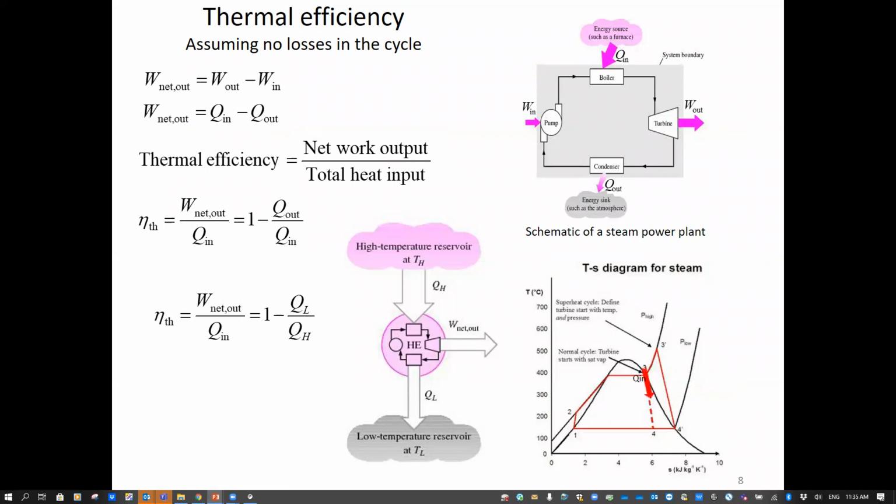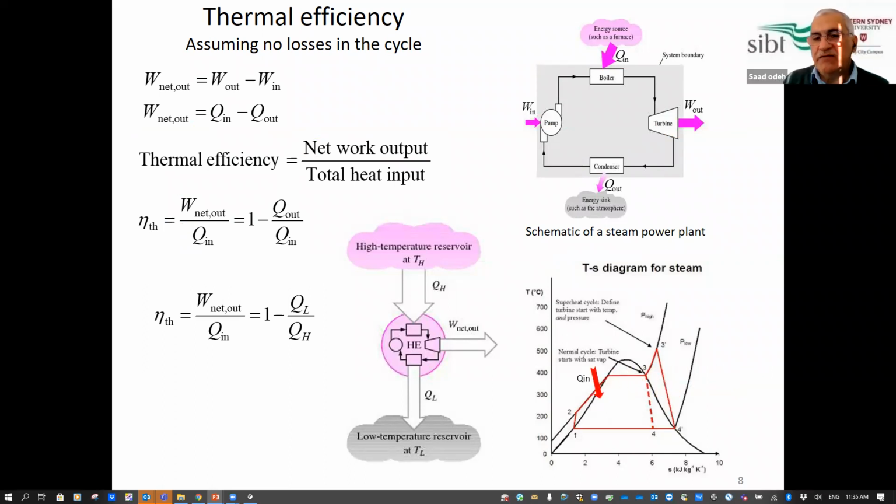All right. So if I want to represent this on a temperature-volume diagram, or temperature-entropy diagram, doesn't matter. That's a process of Q in, the Q added on a constant pressure line, and then there is a Q out, which is the energy removed to the heat sink, which is the river or the surrounding air. Okay.